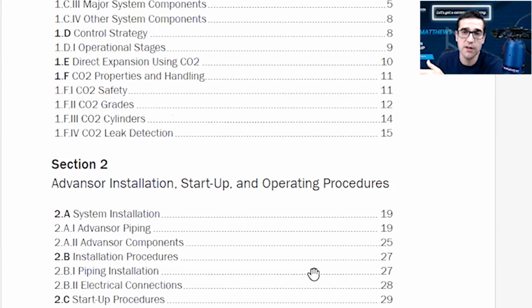And at the end of that one, it shows their defrost section, because I get a lot of people asking, well, how does the defrost work? Every manufacturer is going to do it differently. Some are going to use electric defrost, and I think a lot of that's going to be in the US and maybe even in Europe, because a lot of people say they see it in certain parts of Europe, but it's hot gas defrost here in Canada, a lot. There is some electrical, not too much though, because you can get some great heat.